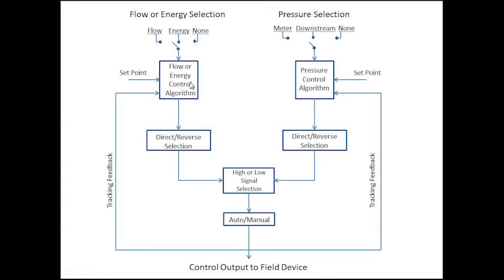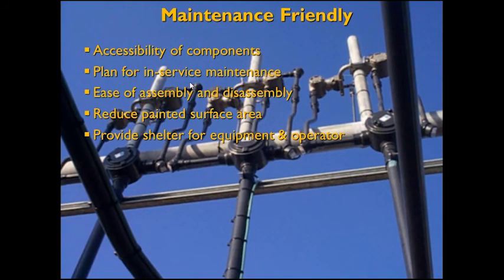If you're a single source supply to a power plant, your control method is pressure control. You're going to feed that plant. You never want it to run out of gas, and you're going to maintain pressure. If you're the third supply to that plant, someone else is the primary or the swing, they're going to be on pressure control. You're going to be on flow control. But it's important that for your project, you know how you interface with the other suppliers to that same plant header. These are all things that need to be considered.